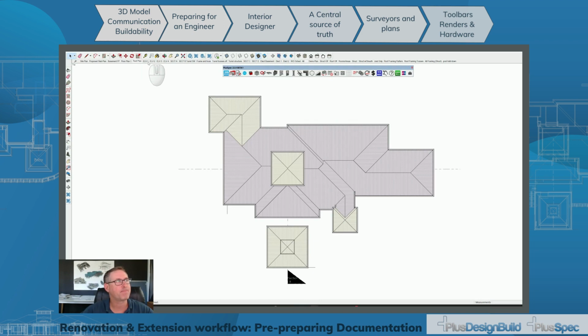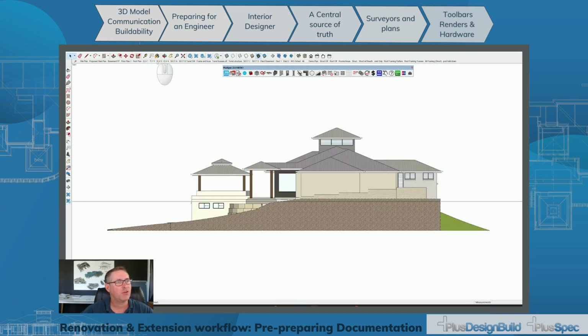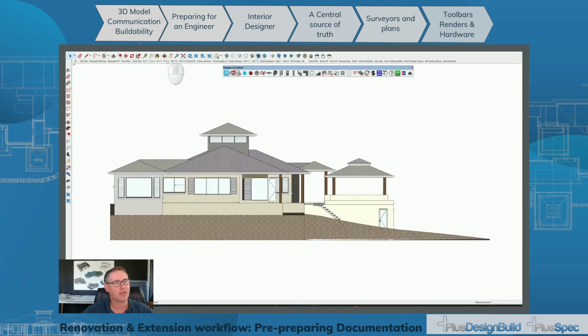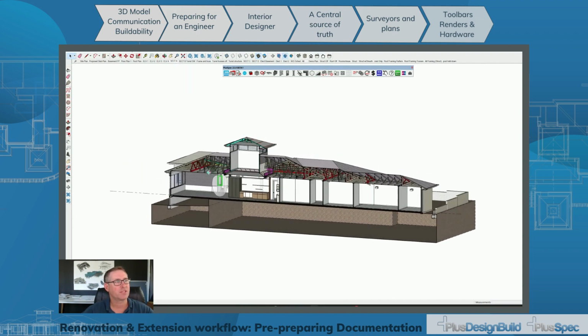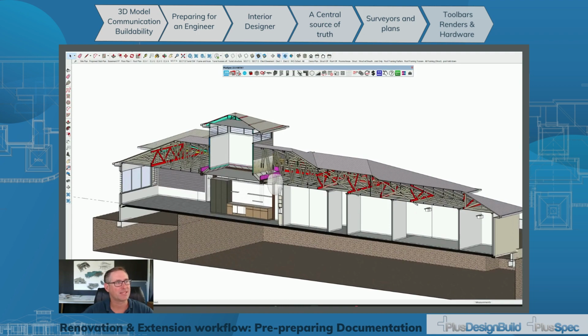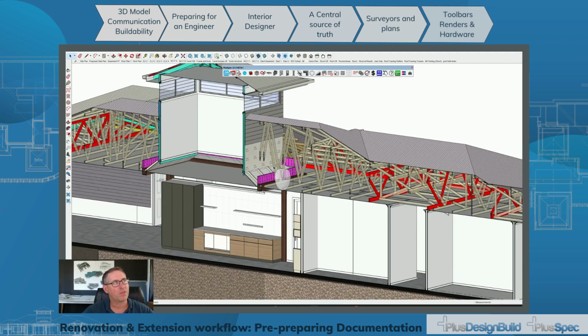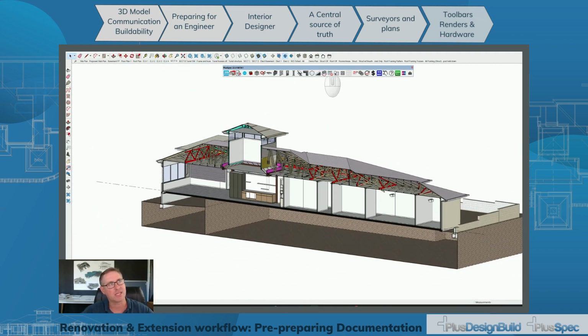Roof plan, elevations. If you don't need some of these scenes, you simply go through and delete them. And I'm going to show you one in a second. Sections, I align my sections. So you'll notice that it's just a cross section of that building. It's actually a live section. So when I make a change, the section updates. However, these sections, I need to position them. And when you actually use the scene tool, it'll create sections for you and you position them.